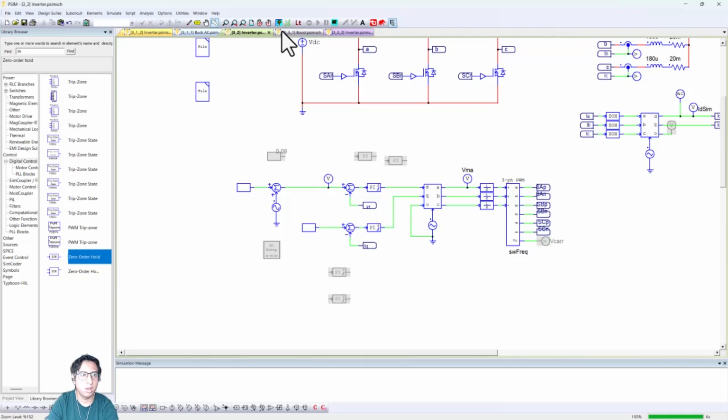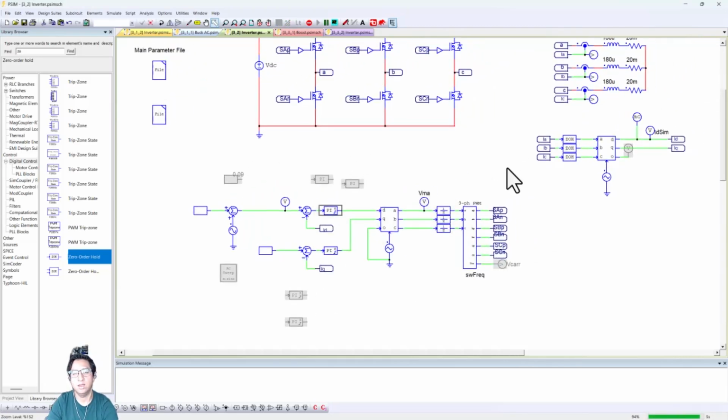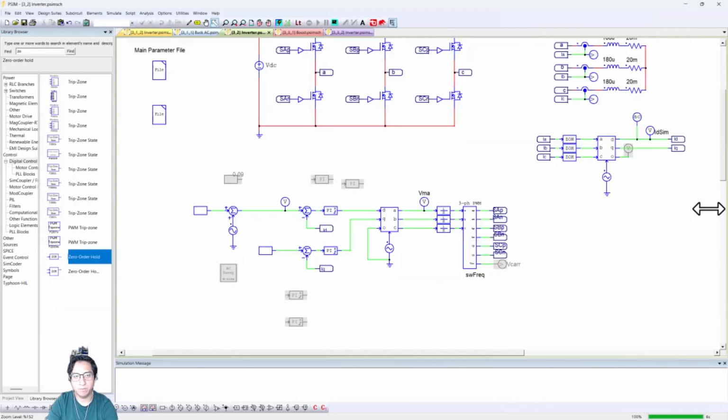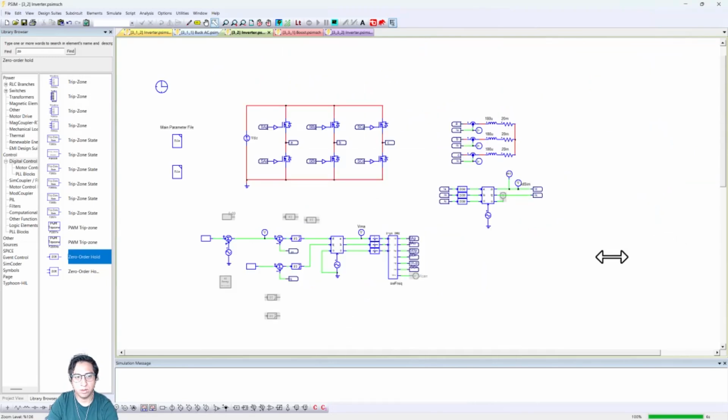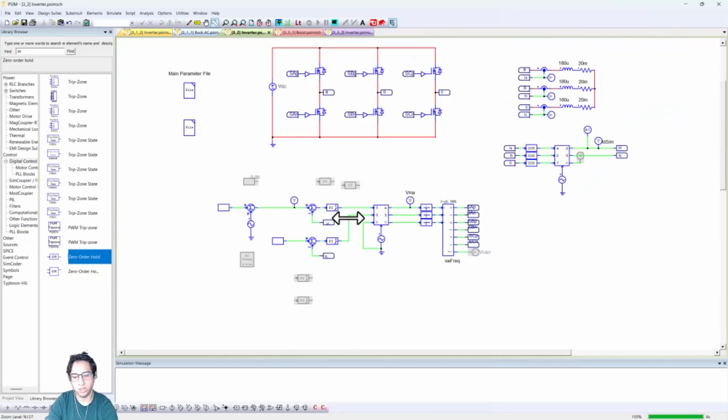And we see these are correct, yes. And we'll see at the phase currents that these actually look much, much cleaner, right? So take this in mind. If you want to change from analog to digital, you need to redesign your controller. It's not going to have the same stability. Okay, now let's look at our next couple of examples.